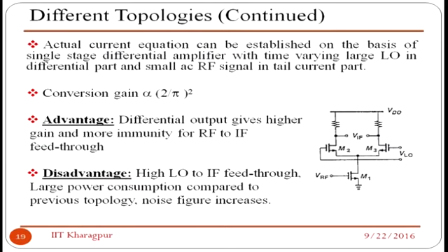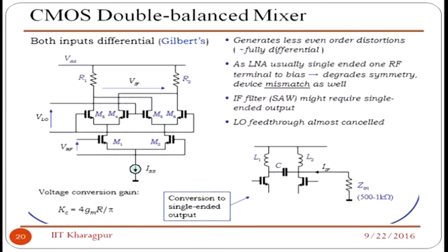So now I am going to the famous double balanced mixer with Gilbert configuration. Essentially the Gilbert configuration is nothing but this. But now we have given a pair of transistors, two differential pairs. So look at here. Earlier it was M1 and M2. Now M3 and M5 and M4 and M6.